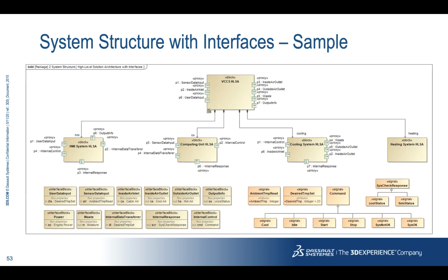Okay, and here we again create the system. We show subsystems, we show the interfaces. What are the main interfaces? Please note that we are not defining connections on this diagram. It is only to identify what the interfaces are. So for every subsystem, we start looking at the black box. We know what the inputs are and we know what the outputs are, but how those inputs are transformed into outputs, that's something we have to figure out. So we have to take every subsystem and we start working on that subsystem, detailing what the main components are, what the main functionalities within it are.